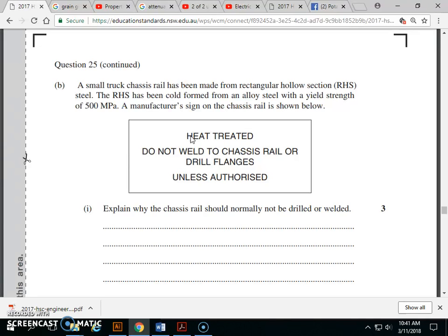There are 3 things that I say are the most important things you need to learn in this subject to not embarrass me, right? First one is you need to know that concrete is made of cement plus aggregates. You need to know that the stress formula equals force over area, unless it's bending. And you need to know that the yield stress of steel, use 300, right? Now, it can be higher. If it's higher, it probably means it's got more what? Or more